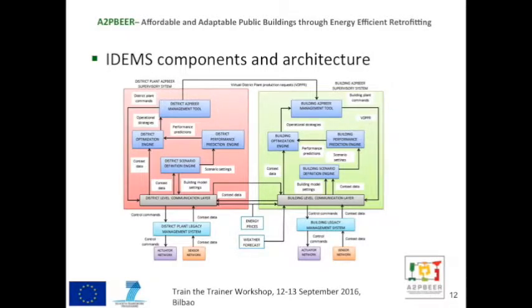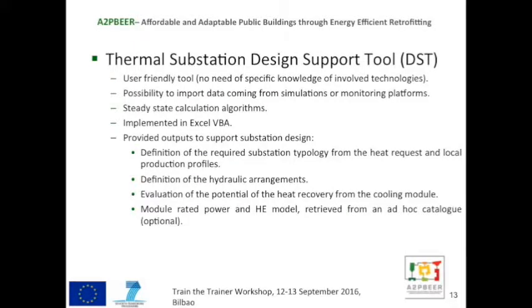Additionally, in order to facilitate the implementation of this kind of thermal network concept, we have developed a design support tool in order to facilitate the design and dimensioning of the innovative thermal substation that I have just explained. So this is a very user-friendly tool that has the possibility to import the heating demand, cooling demand, and local production profiles that are used as input data from simulation programs, or in the case of already existing district heating systems, from monitoring platforms. It is based on simple but reliable steady-state calculation algorithms, and it has been implemented in Excel in order to make it very user-friendly.